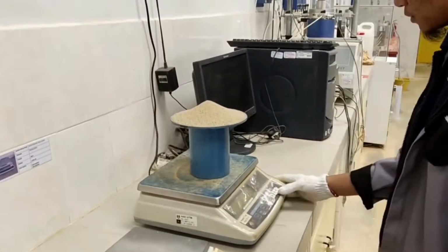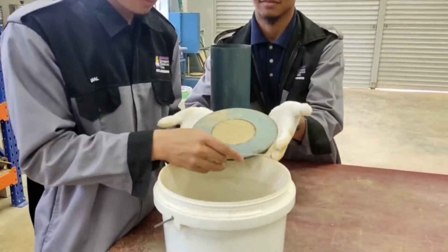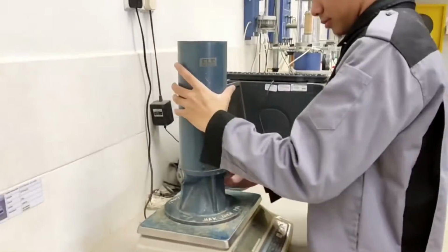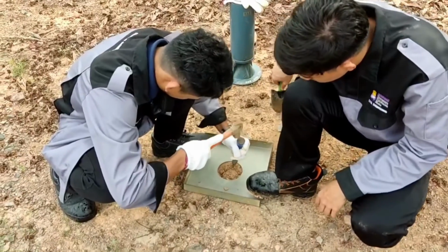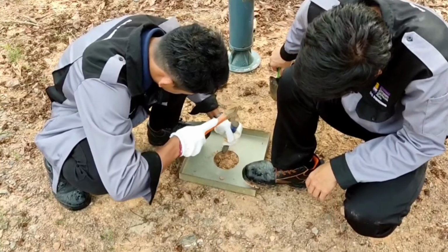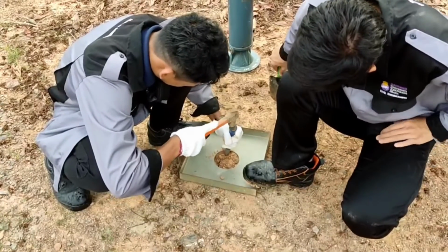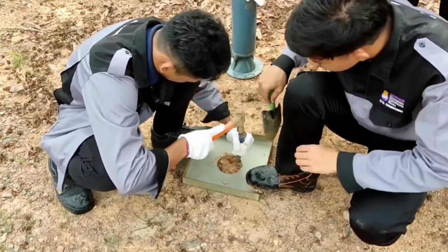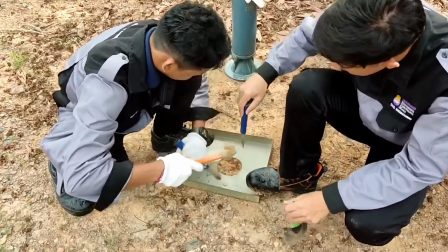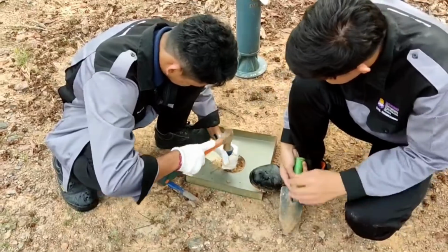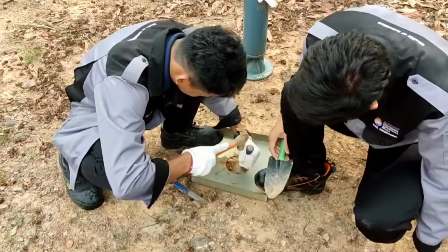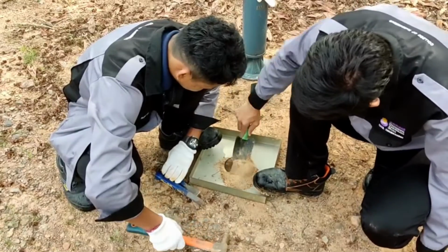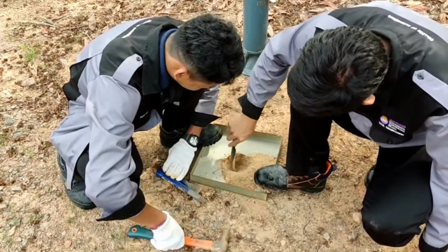The first part is the calibration stage, to determine the density of sand to be used by using the calibration cylinder. Okay, let's go to the next part, which is sampling for bulk density. First, the metal tray with the center hole is placed on the prepared surface. Then, using the center hole as a pattern, the soil is excavated using a trowel up to the required depth, and the loose soil is carefully collected in the metal container and weighed.